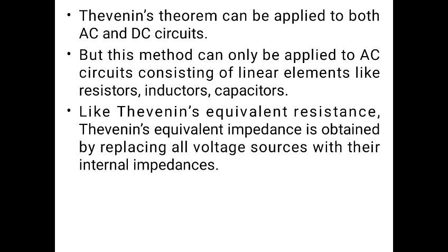Thevenin's theorem can be applied to both AC and DC circuits, but this method can only be applied to an AC circuit consisting of linear elements like resistors, inductors and capacitors. Like Thevenin's equivalent resistance, Thevenin's equivalent impedance is also obtained by replacing all voltage sources with their internal impedances.